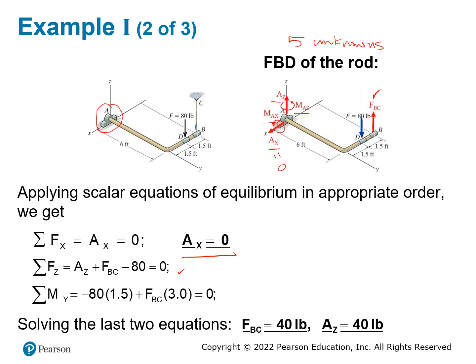When you do the moment equation, you need to select the reference point. And I always tell you, try to find the point that you can minimize things, right? So this moment here is the z direction moment. This moment here is the x direction moment. And what is the y direction moment? The y direction moment is going to be 0 because there's no reaction moment in the y direction.